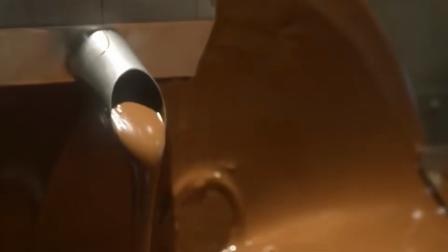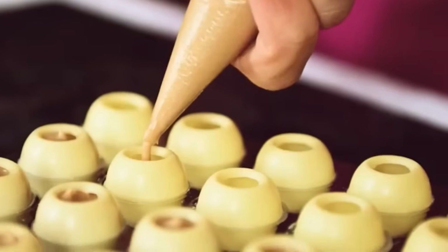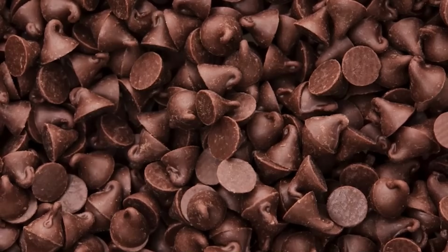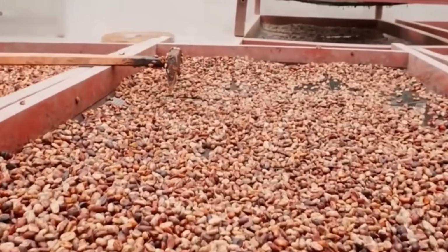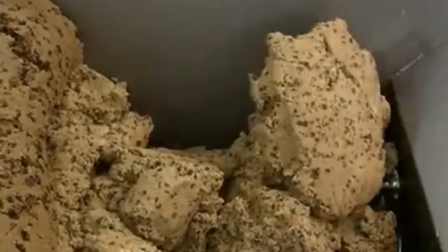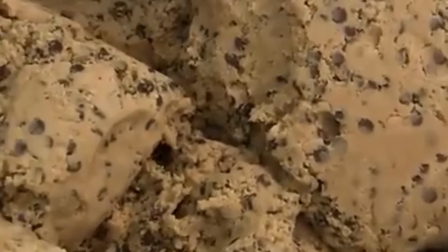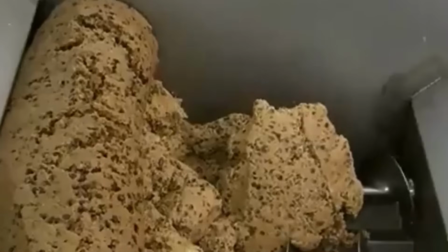Each cookie passes under a vision inspection system equipped with high-resolution cameras and infrared lighting. Software algorithms evaluate cookie shape, surface cracking, chip dispersion, color uniformity, and diameter tolerance. Any cookies failing to meet visual standards are rejected using high-speed air jets. All rejected cookies are weighed, logged, and diverted to waste bins for offline handling.